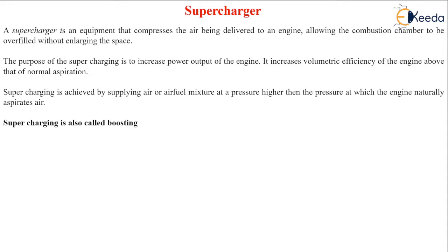Since it accommodates a larger quantity of air in the same amount of space, the volumetric efficiency of the engine will increase compared to a normally aspirated engine, that is, an engine which is taking in the air at normal atmospheric conditions of pressure.